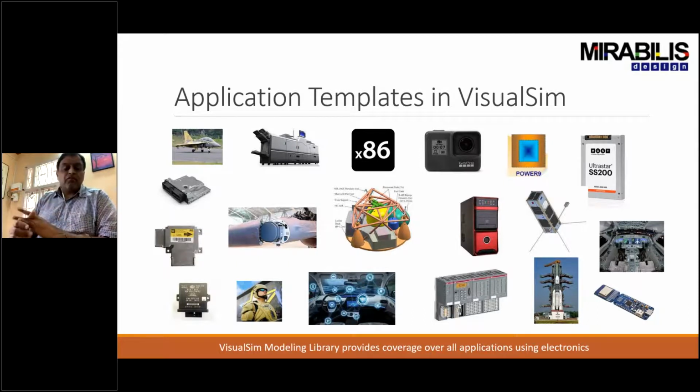and then we can see what the performance is going to be when we apply the faults. So the idea is to see, does it recover after the fault occurs? So for example, say the RTOS has multiple slots, and say a task which is in slot 2 always overlaps into slot 3. What do we do? The first thing we do is we shut down the slot and then try to restart it and see if the problem goes away. So that would be part of the model and part of the experience that you would note for your user, so that they can modify that part of the system.